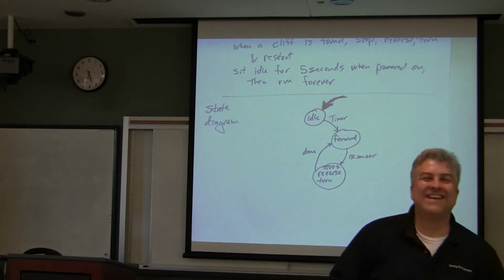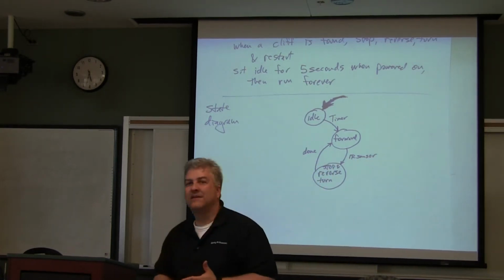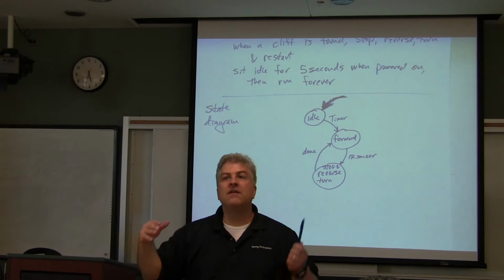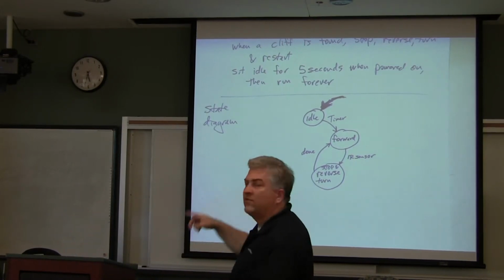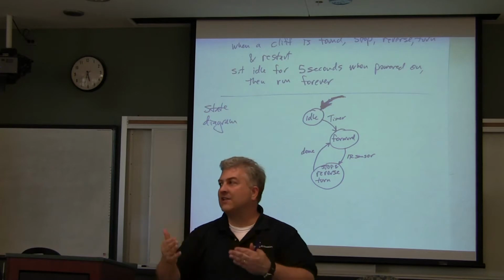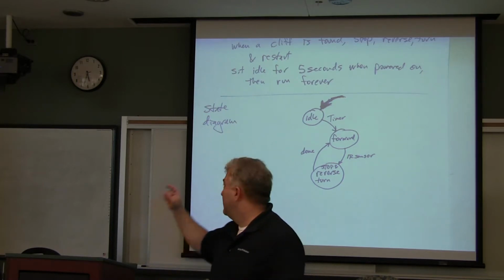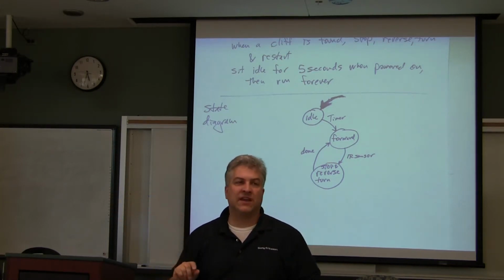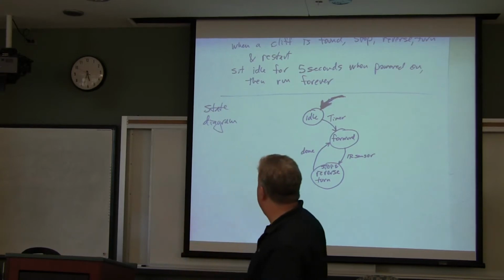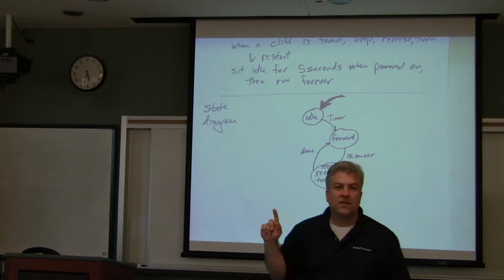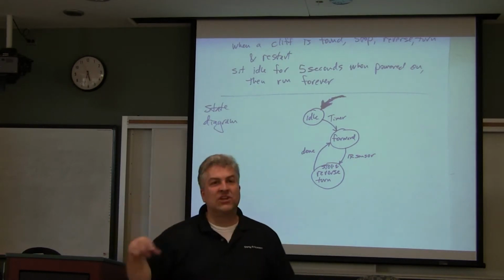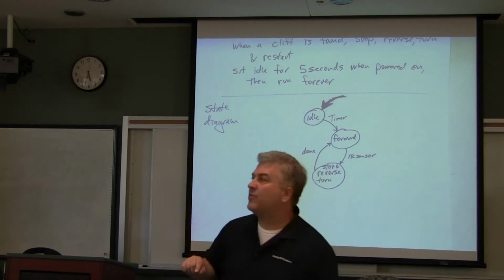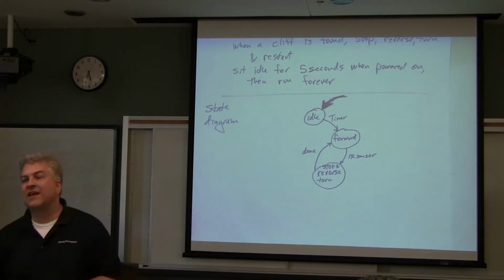Ignore it, okay, guys? So there's some sort of microprocessor event, like a timer ticking down 5 seconds, after which it'll go to the next state, which is regularly running forward. It has its outputs, it's constant, and based on some trigger, in this case the IR sensor, it'll stop and move to the next state. The next state could have several movements, in this case stop, reverse, turn. And in fact, once it is done doing all of those, because it's software, you could also move out of that state into another one based on completing the activity.